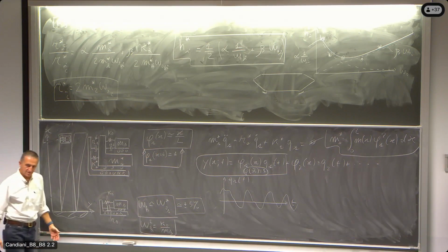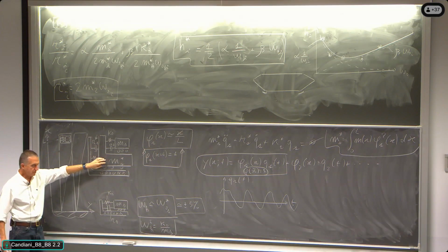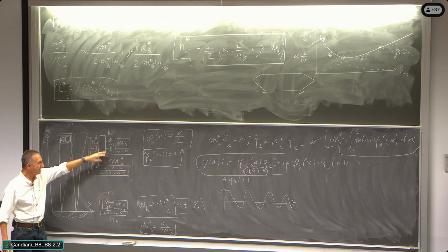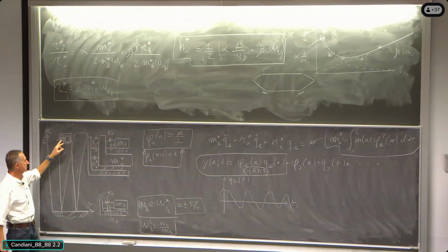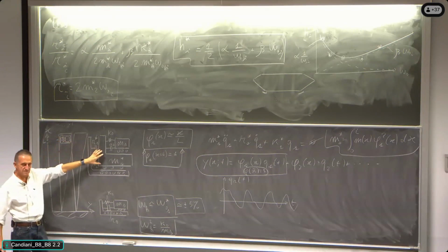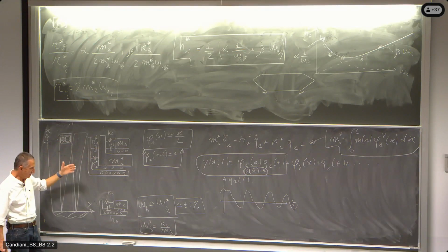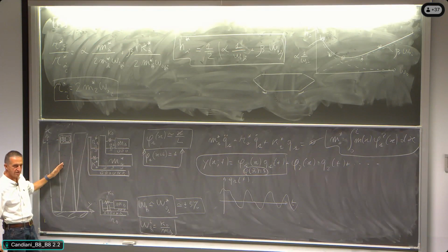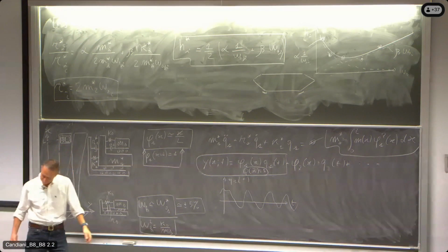It gives a physical meaning to what we do. So it is meaningful to give a modeling like that, to say that I have one mass M1 star, and another mass connected exactly by those stiffnesses and dampings that I have here. All right? This is a very simple model of this object, taking advantage of the modal representation of the building, using just one mode, that is enough, because we want to protect that, and adding the TMD. All right, numbers.